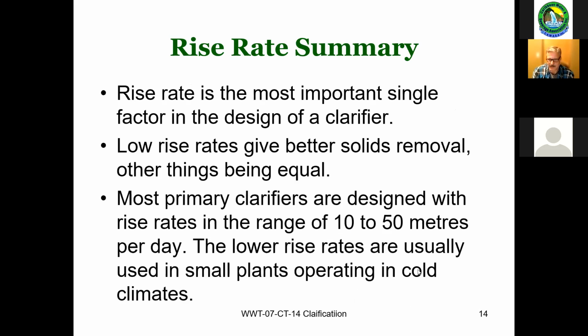So a smaller plant in a colder climate needs a lower rise rate, which is less flow through the tank, so you can get those solids to settle out. There will be a question, I would assume, on rise rates, just to make sure you understand what exactly is happening there.